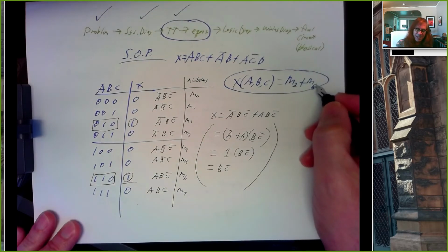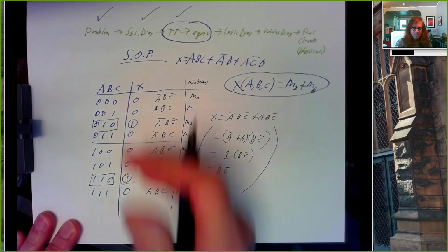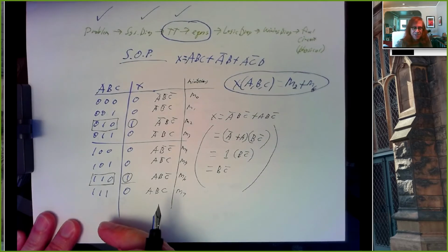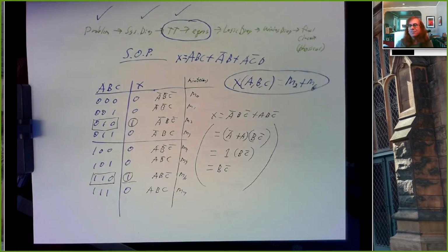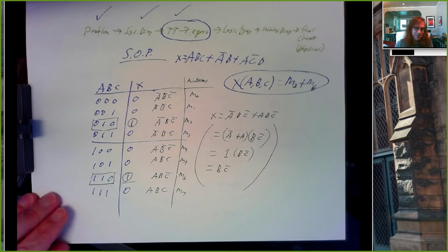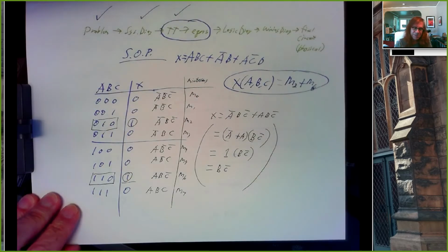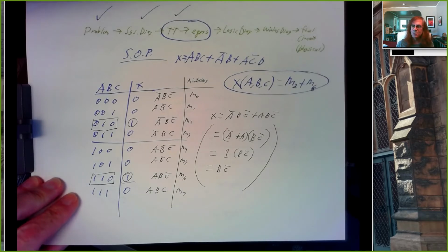So if I have an n down here, when I look in the nth row, my output function should be 1. And in the nth row, if I look at my inputs, they should look like the binary version of n. You'll notice that pattern as you go through the homework. You can use that pattern so you don't have to actually write out 64 rows. If you have a function with 6 inputs, you can start to find some shortcuts.